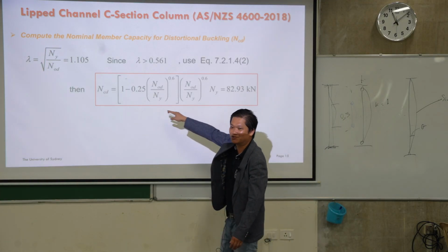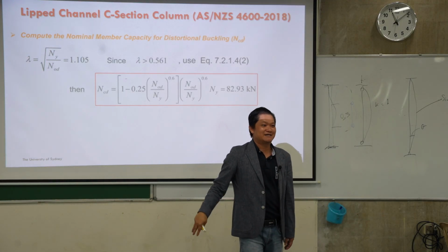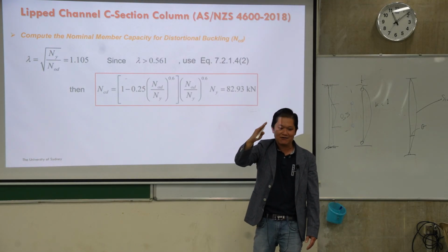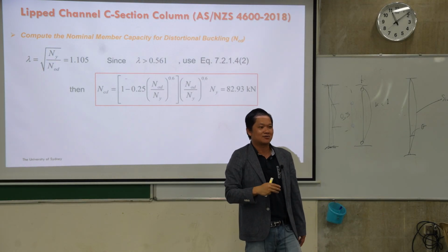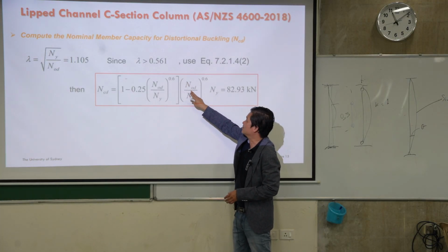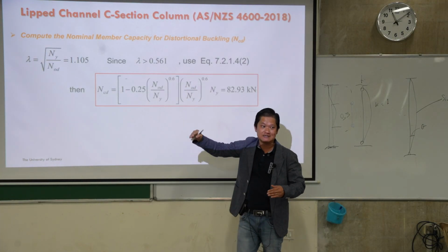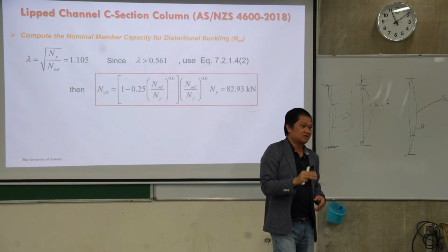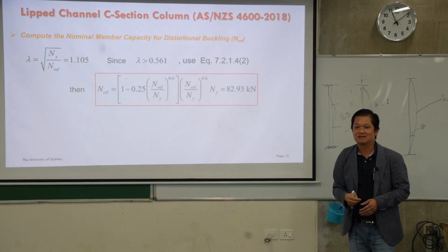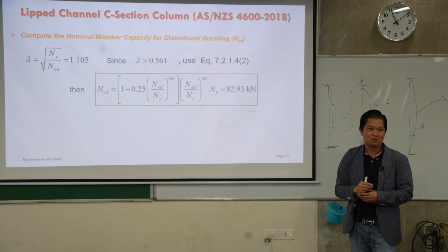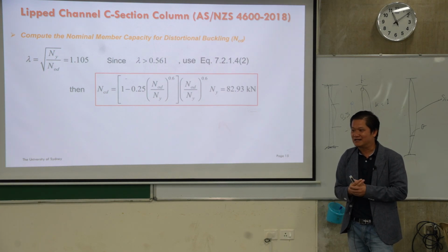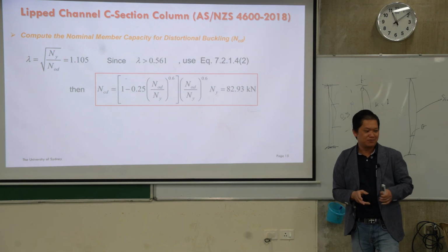We still have to do curve fitting. This is actually curve fitting for the test. We just bring it down and up, calibrate the direct strength curve, but built in that we got the behavior. So we got the local buckling, we got the yield stress, and in the end it works. But it's still semi-explicit empirical equation. So we're getting there.